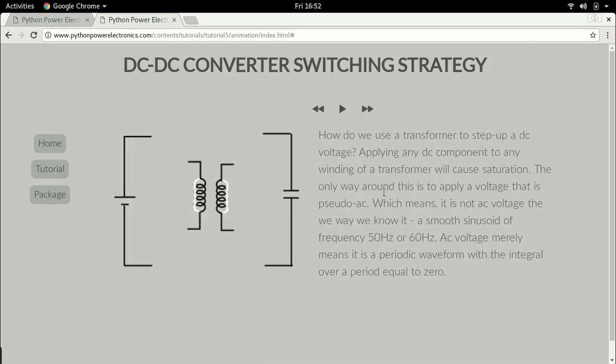So now let's look at our old option of a transformer. We usually use transformers to a great degree in a power system, but usually we use a transformer for an AC system. Like in this case, we are looking at two DC sources. We are looking at a PV panel of around 30 volts wanting to be boosted up to 300 volts, again DC.